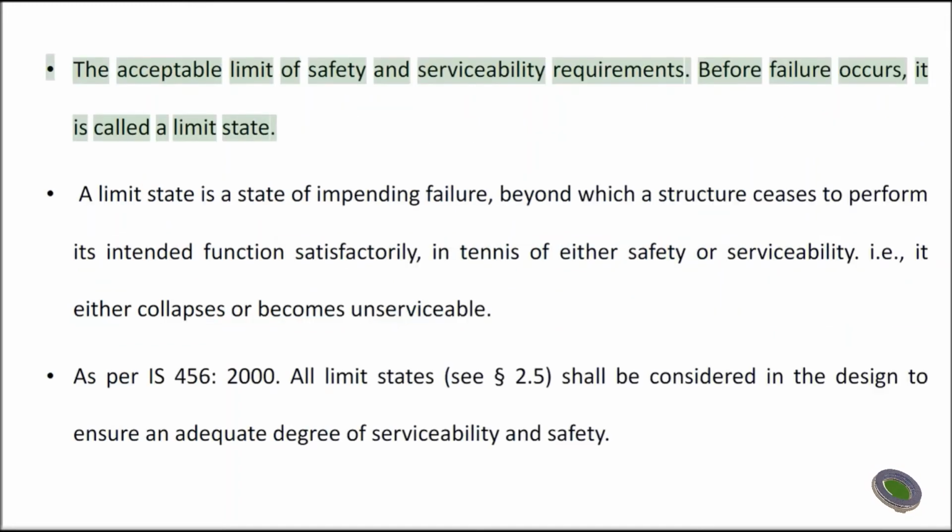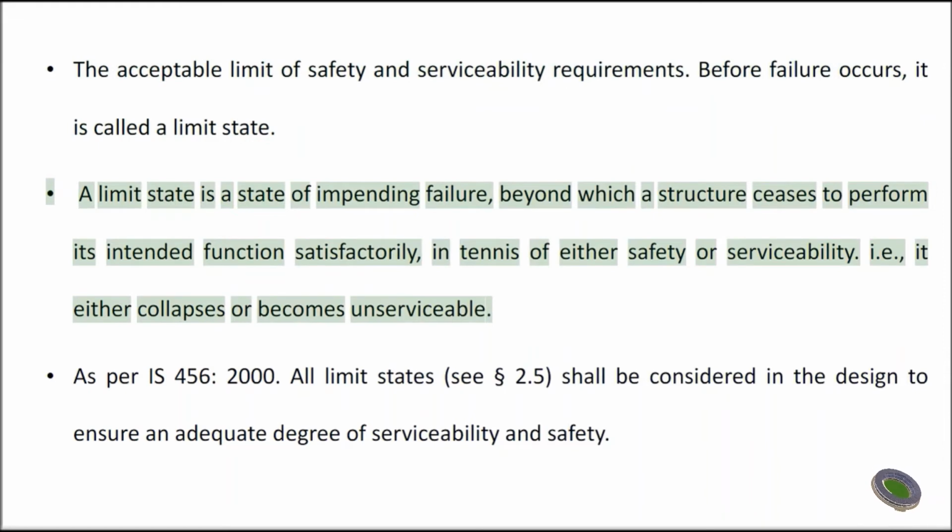The acceptable limit of safety and serviceability requirements before failure occurs is called a limit state. A limit state is a state of impending failure, beyond which a structure ceases to perform its intended function satisfactorily, in terms of either safety or serviceability, i.e., it either collapses or becomes unserviceable.